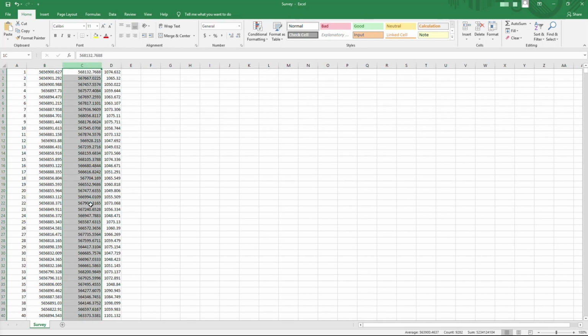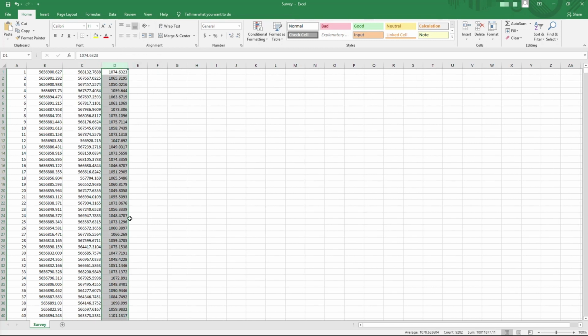The third column here is our easting. And again, I can tell that by 6 decimals, and I also know what coordinate system I downloaded it from. And the fourth column here is the elevation of the point. So we have point number, northing, easting, elevation. Sometimes there's a fifth column with description. So this would say something like road center line, and the next one would be road center line, and you could logically map them out. However, this file doesn't have that information.